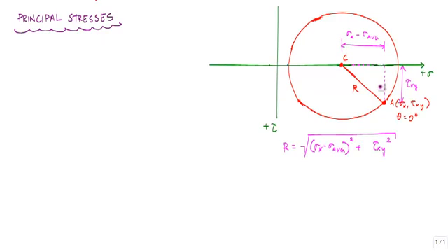And in Mohr's circle, that is just here: this is the maximum normal stress, sigma 1, and here is the minimum normal stress, call that sigma 2. A lot of times sigma 1 is referred to as the major, and sigma 2 is referred to as the minor. You will notice here at this point that the shear stresses are 0, which means that this is in a pure normal stress state.